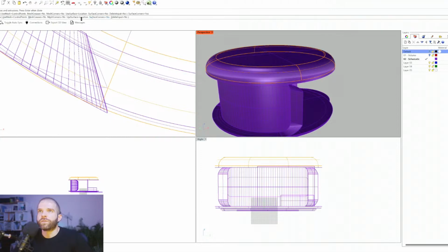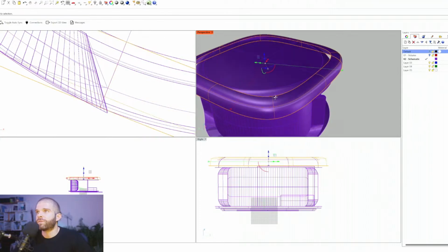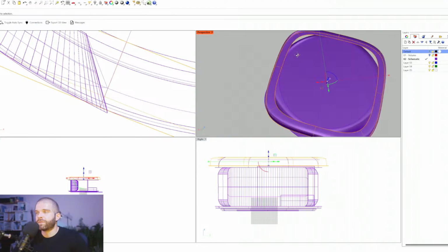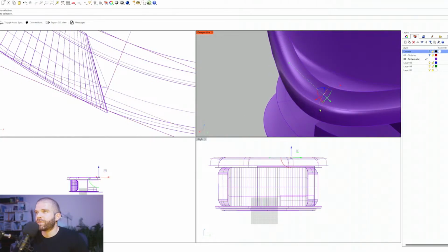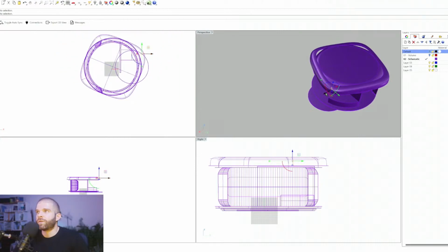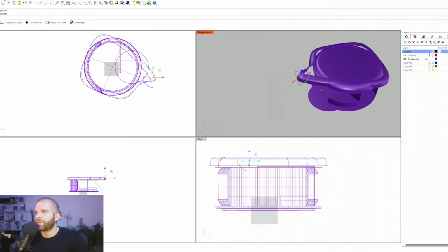So surface corners, yes. Use surface control points. Delete input, no. We'll hit enter. So the sub-D is a little weird, like obviously it didn't fit fully, but sub-Ds are a bit more friendly. They're basically just curved meshes when I try to push and pull their faces. So you can see there, it's not taking very long like it was before.